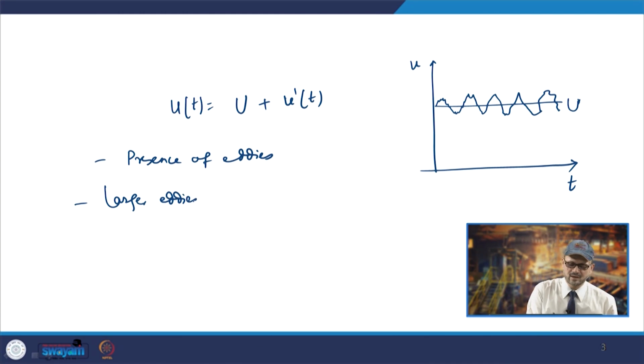Before that, when we were talking about turbulence, we talked about the smaller eddies and the larger eddies. The larger eddies are basically dominated by the inertia effects, and the viscous effects are negligible in that case. So, normally the larger eddies are basically inviscid, or effectively inviscid.